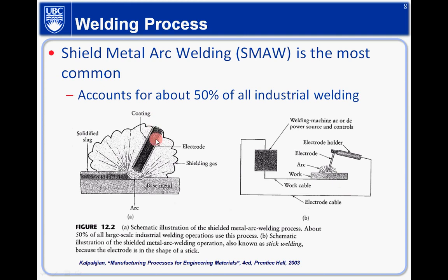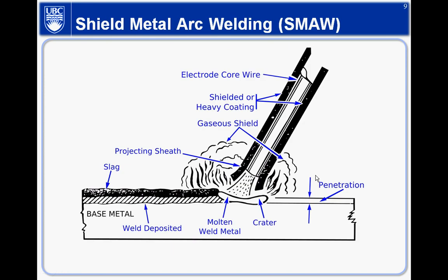So when you do the welding, the heat will melt the flux, and the flux forms a protective shield protecting the welds from oxidation. The shortcoming is that it forms a so-called solidified slag as you go along the metal, so the slag needs to be scraped off after the welding. So that's stick weld. And there's power going through the electrode which causes an arc. Here's another picture talking about the same thing: the inner side is the core material, and outside is the flux.